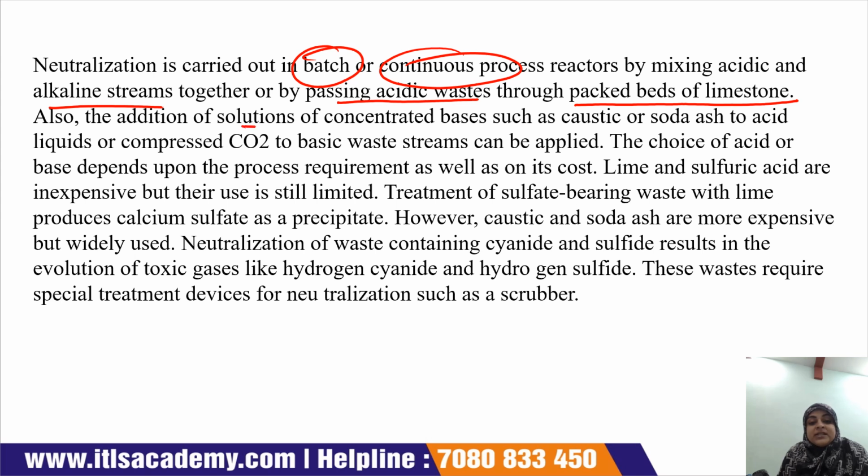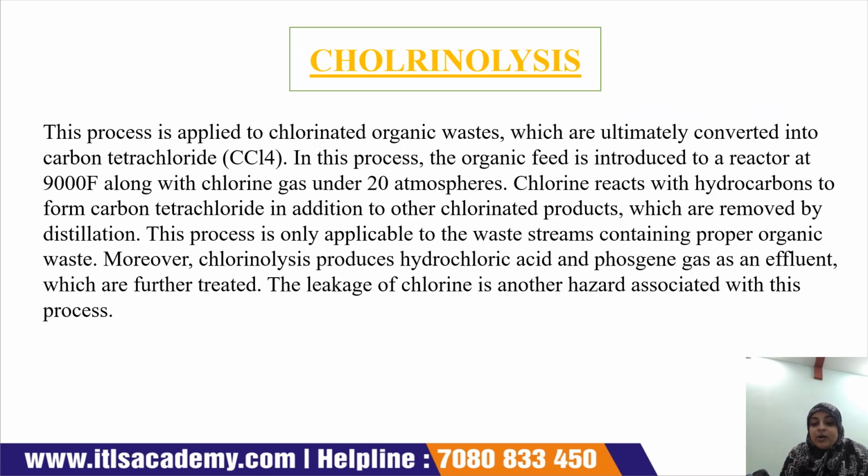Now, a solution of concentrated bases like caustic or soda ash can be added, or for a basic waste, acid, liquid or compressed CO2 can be applied in treatment. The choice of this acid or base depends totally upon the process that we require, and also on the cost of that process. Now the next is